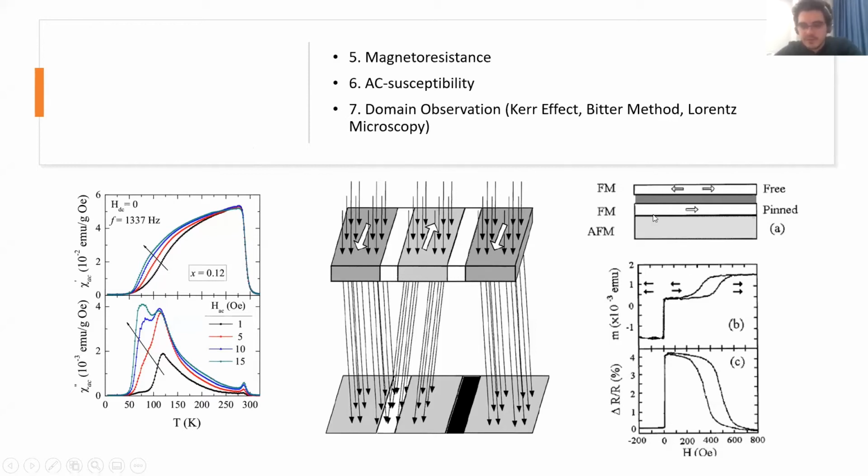From this magnetic tunnel junction with applied current and field, we can see a hysteresis loop just here and here, which gives the dependence of R on applied field and magnetization on applied field, giving us the ability to calculate the coercive field and exchange field of our fixed layer. These FM, AFM materials are used as fixed layers in spin-torque oscillators and in other technologies.